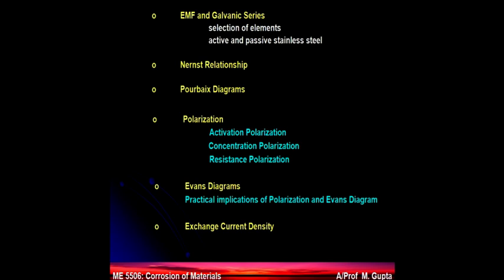It's a natural occurrence. Once oxide layers form on the surface, activation polarization kicks in. After that, concentration polarization kicks in. After that, resistance polarization kicks in. Apparently, the reactions start to slow down. From the corrosion perspective, it is good, but from the battery technology perspective, it is not good. So you have to understand these three things from that perspective.